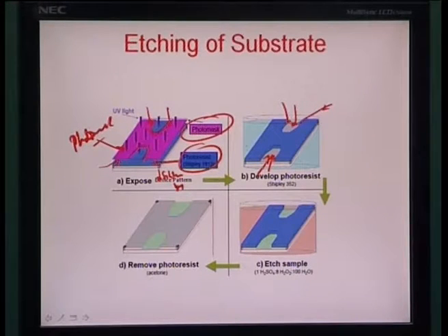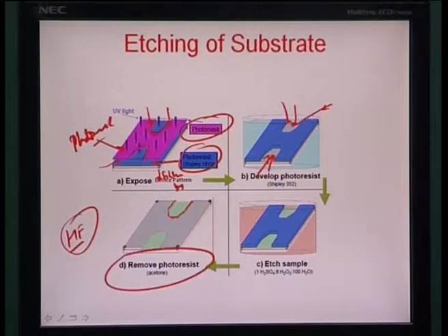The other portion is a sacrificial cover over the silicon surface. Now, you could use some kind of acid, maybe HF or aqua regia, to etch this layer up to a certain depth and then remove the photoresist over it. So, this is the etching process.